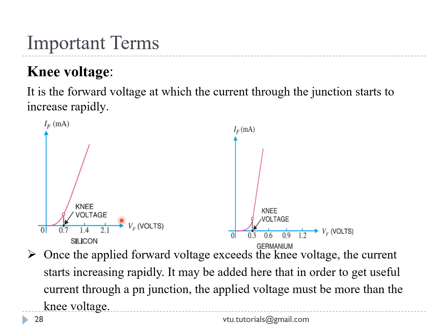The voltage from 0 to 0.7 is required to overcome the potential barrier for the free electrons. Once this 0.7 is reached, there will be a sudden flow of electrons and the barrier breaks down, so that the electrons flow with higher current production. This is in the forward biasing of the PN junction.